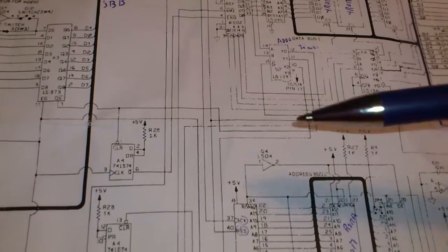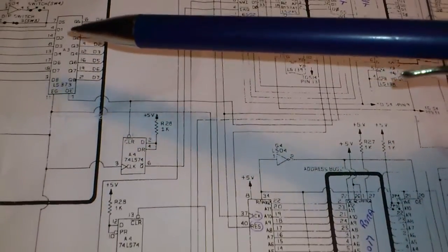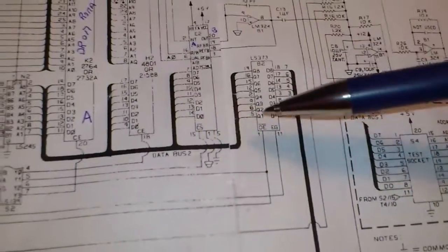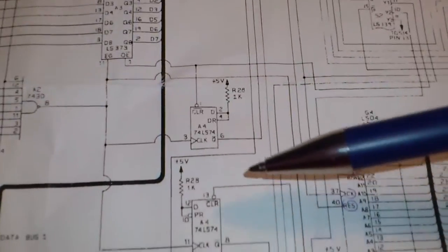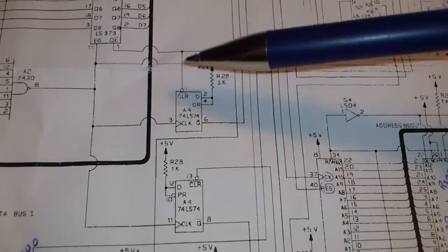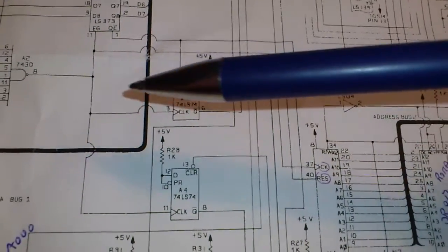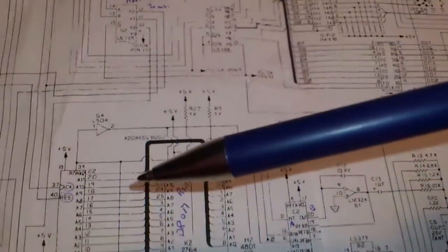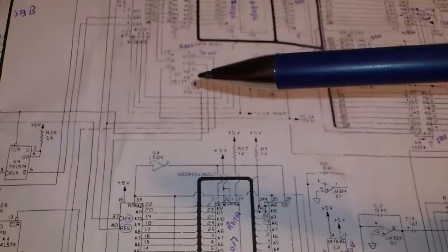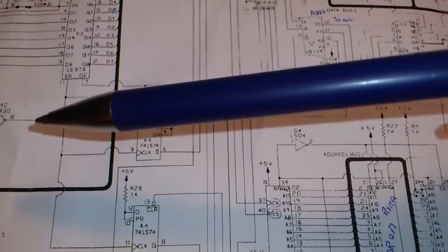Then the CPU reads out the sound code from that one or that one, and releases its interrupt line again by clearing it on that side and on that side. So if a sound code comes in, the interrupt on both CPUs tells them there is a sound to be played, and they fetch the sound code so they know which kind of sound to play.